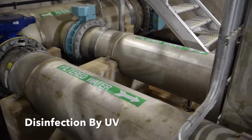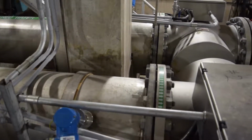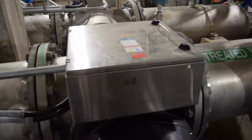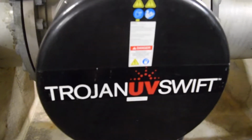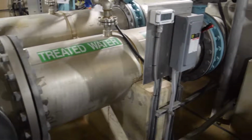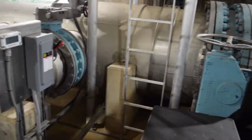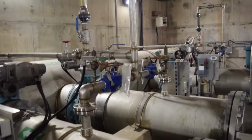This process consists of 5 Trojan Swift ultraviolet reactors, each rated at an approximate 30 megaliters per day. Each reactor consists of 4 9.4 kilowatt medium pressure ultraviolet lamps, which when running are powerful enough to inactivate pathogens, making them unable to replicate and therefore harmless to humans.